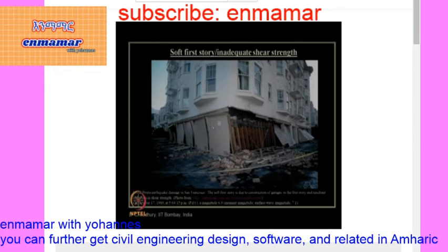If we use that soft first story, it creates maximum collapse when a major earthquake occurs at that site, because of no bonding or no adequate connections between the members. So it is always preferred to provide some bracing system or connection system to avoid this soft story effect. This is called soft story, where there is no infill wall in between columns and so on.